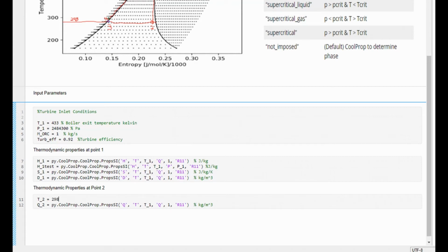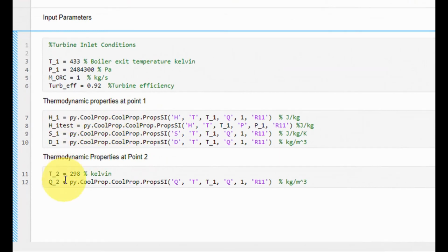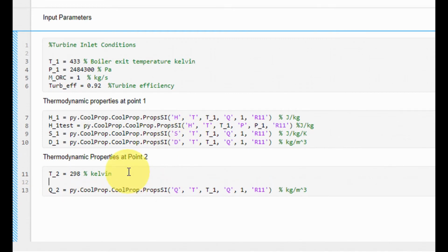You could also find the pressure at T2, and T3. So it's also going to be the same pressure. It's because it's a constant pressure line. So it goes here, constant pressure, and then it heats up. So we can quickly obtain the pressure. Come to think of it, we don't need the pressure to obtain the quality of the fluid. All we need is the temperature and the entropy. So the entropy at point 2, which is s underscore 2, is equal to the entropy at point 1, s underscore 1.